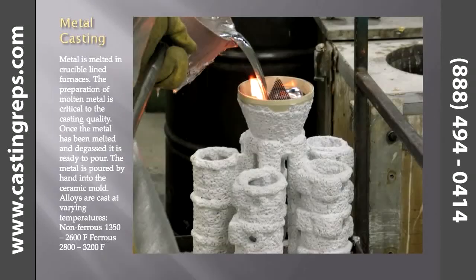Metal casting. Metal is melted in crucible-lined furnaces. The preparation of molten metal is critical to the casting quality. Once the metal has been melted and degassed, it is ready to pour. The metal is poured by hand into the ceramic mold.